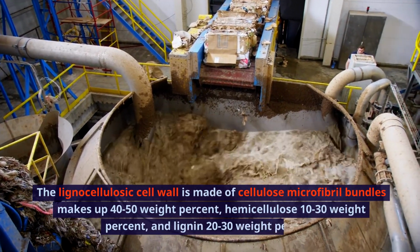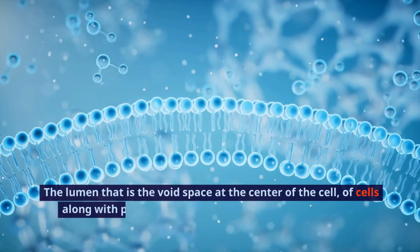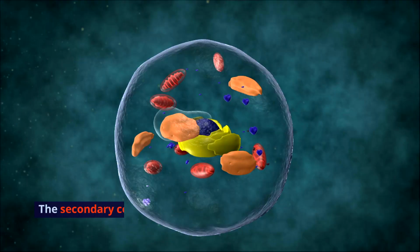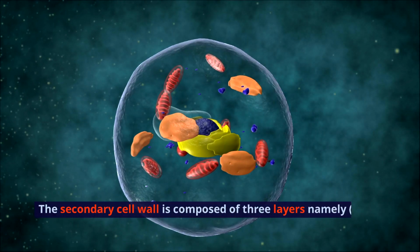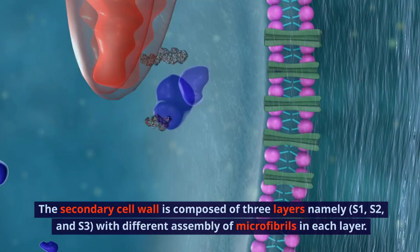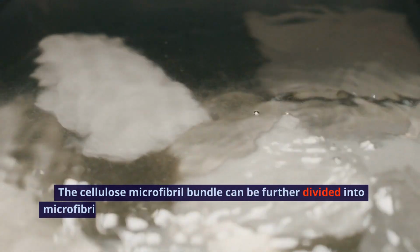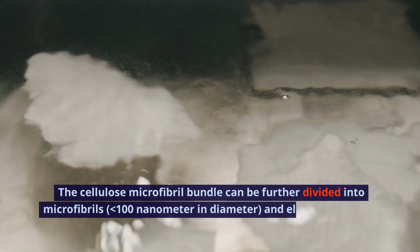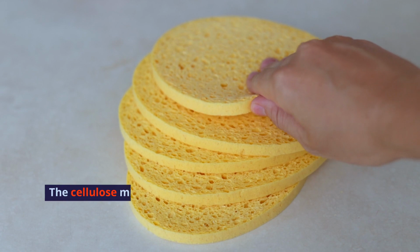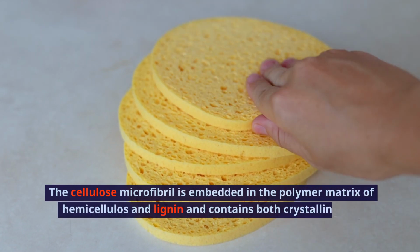The lumen, that is the void space at the center of the cells, along with pits traversing the cell walls, constitute the 3D transport network in wood. The secondary cell wall is composed of 3 layers, namely S1, S2, and S3, with different assembly of microfibrils in each layer. The cellulose microfibril bundle can be further divided into microfibrils, 900 nanometer in diameter, and elementary fibrils, between 1.5 to 3.5 nanometer in diameter. The cellulose microfibril is embedded in the polymer matrix of hemicellulose and lignin and contains both crystalline and amorphous regions